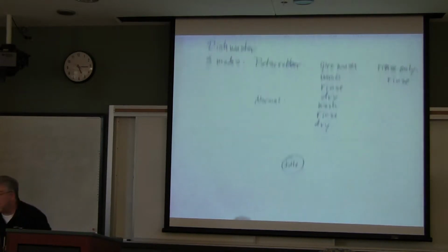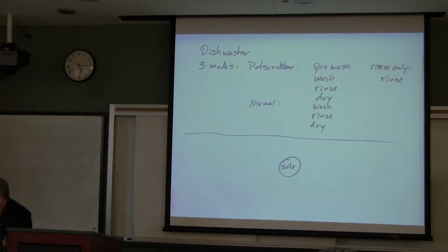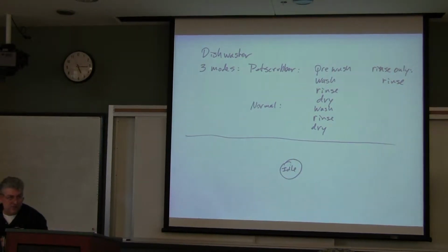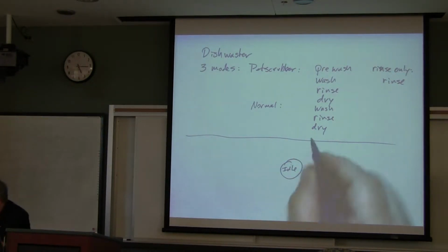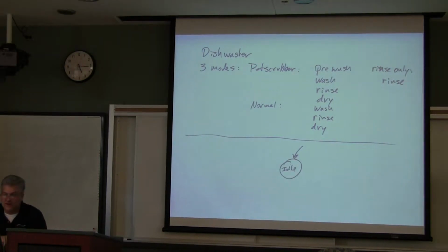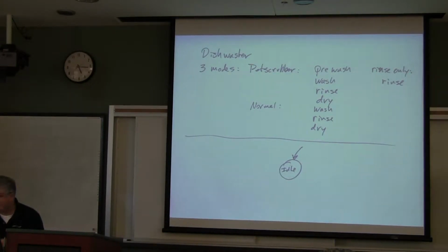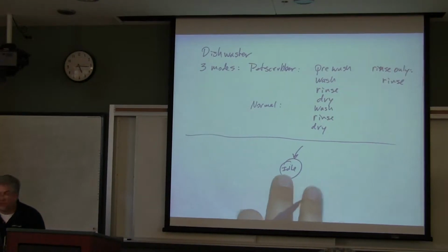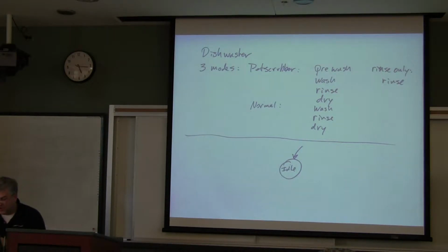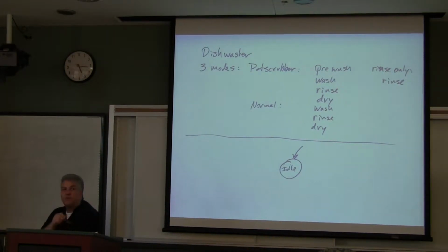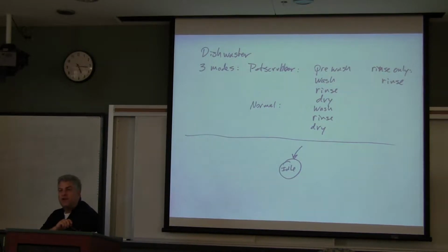So, you will always start in the idle state. And by the way, when you have an initial state and you first power on your machine, you want it to go to something. It's always good to go at power on to the idle state. Should you have an initialized state before the idle state to set all the values to 0? When you first power up a microprocessor, it does all the setting, and then it just sits there and waits. That is the idle state.